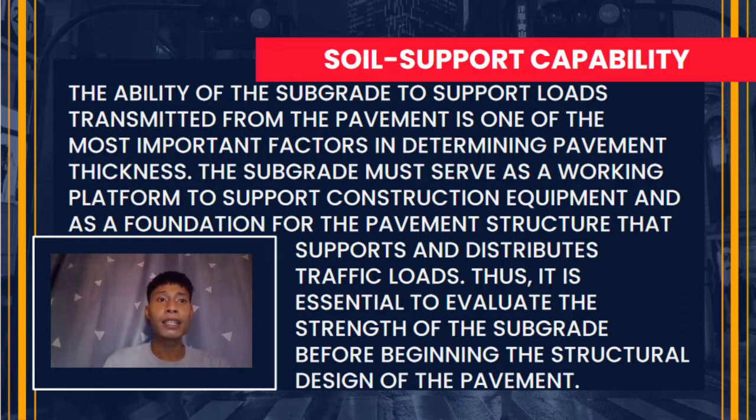So subgrade is a native material that is found underneath a constructed road or a pavement. The subgrade must serve as a working platform to support construction equipment and as a foundation for the pavement structure that supports and distributes traffic loads.